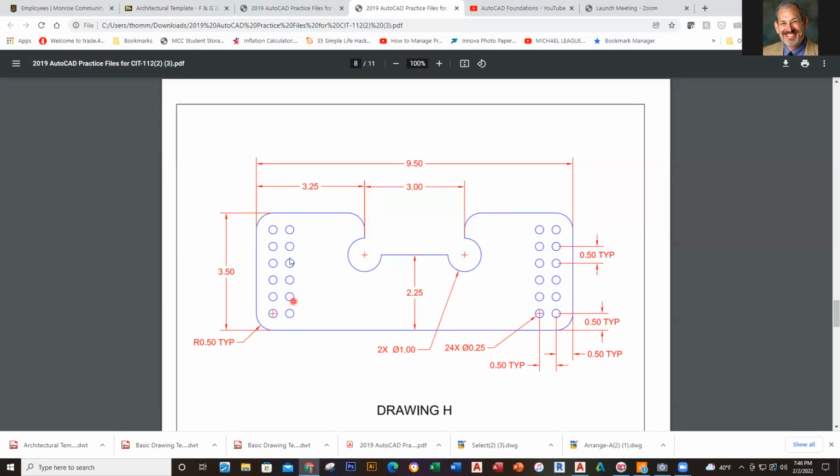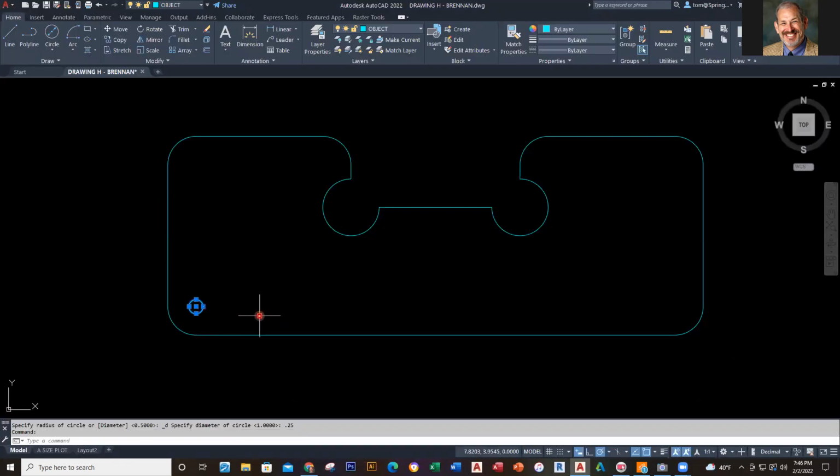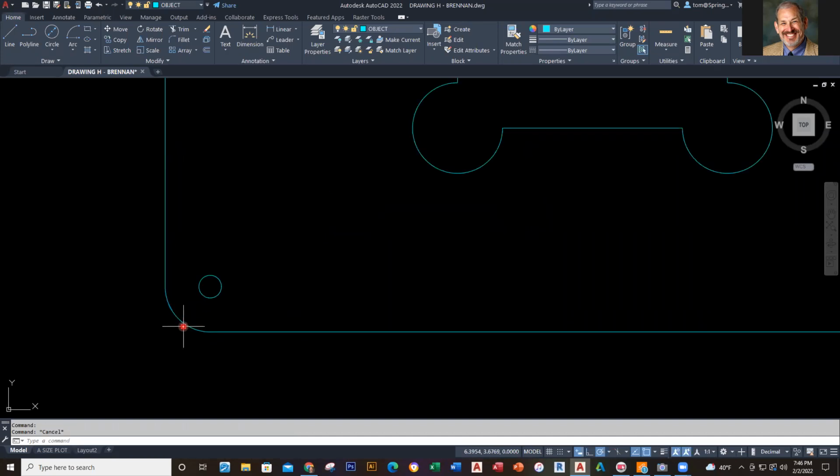Now I can build an array. Once I've got that, I can build an array out of that when I do that. So I just want to make sure the circle is there and it actually shares the same location as that right there, which it does. So if you want to check it, you click on this and you should see that its center point lights up in the middle of your circle. That's how you check it.